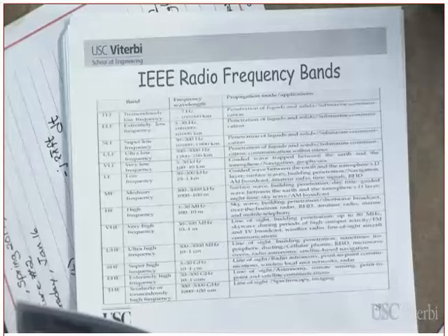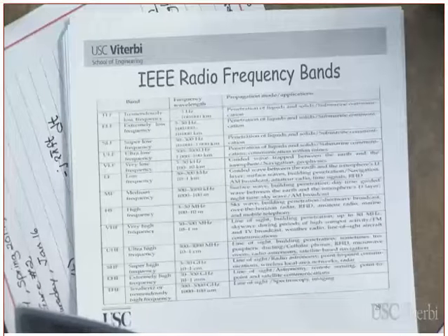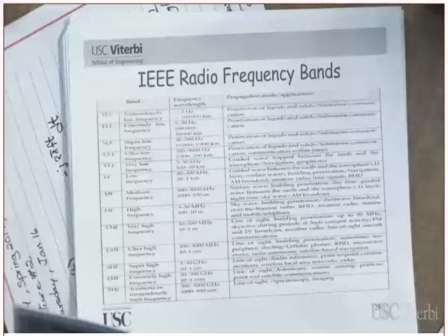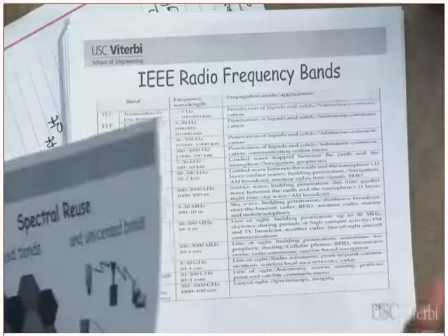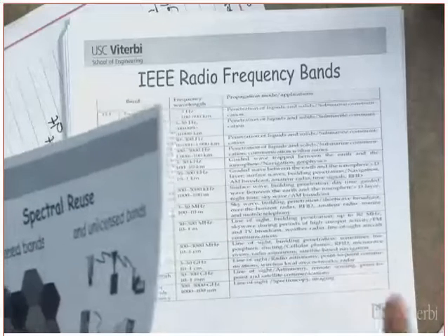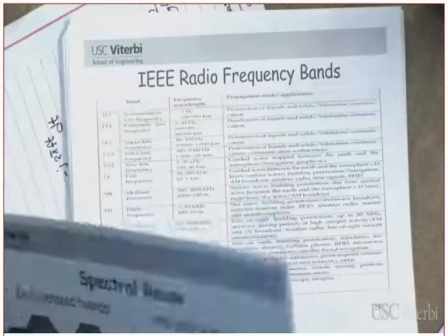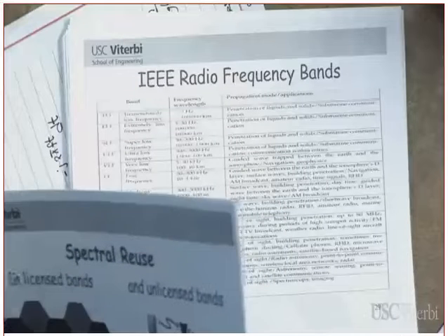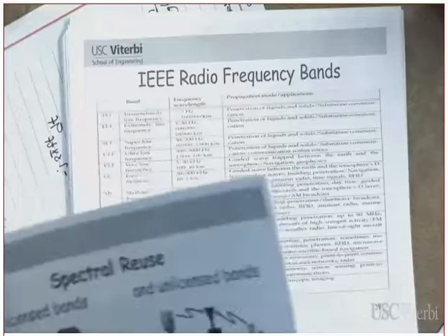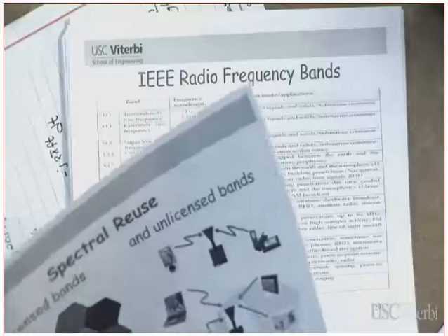Okay. Why is operating at very high frequencies not desirable? The signal, by the way, loses its strength. The signal loses its strength faster at higher frequencies. So the operators, they are in the business of making money. They want to generate revenues. If the coverage is going to be limited, then what will happen? You are going to reduce the revenue, reduce the coverage.